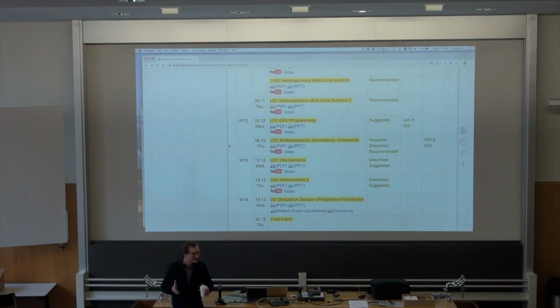And they cannot always fix it. Some of them get fixed, of course, over time, potentially, if they figure out how to fix it while in the field. If they can change the instruction sequence, for example, if you can detect the pattern, you can change it in the microcode potentially with microcode updates, or software updates. But some of these things are not possible to fix. And if you look at those errata, a lot of them are related to consistency and coherence.